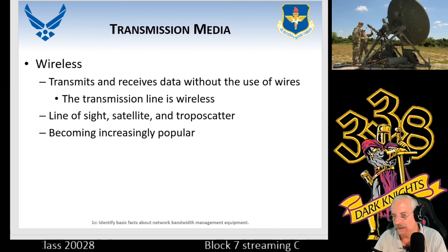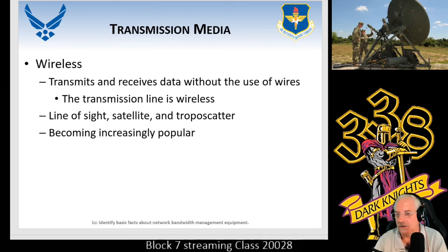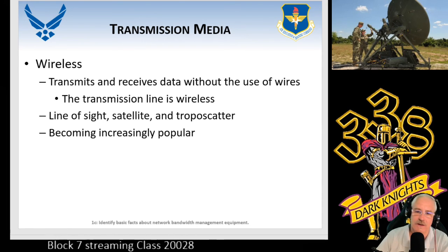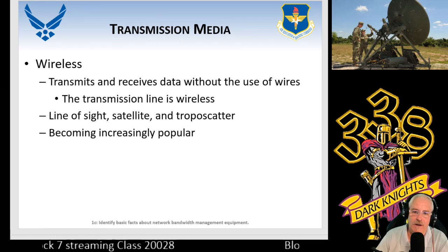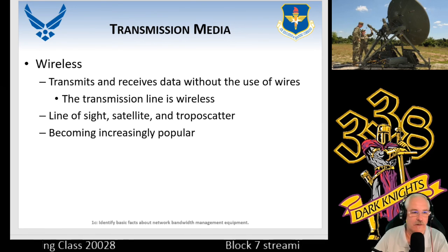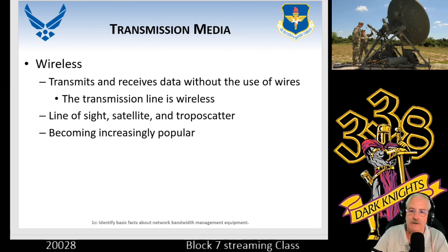Cables are becoming more and more expensive to put in the ground, whereas wireless over the air doesn't cost anything to put the cables, but it does have a backlash because I think the NTIA wants to start cutting down some of those frequencies to where they can fit more frequencies in there. What does that mean? Well, if you've got a 25 kHz bandpass, they want to cut it in half to give you 12.5. Pretty soon it will be 6.25 for that bandpass. So it's getting crazier as we increase our technology.